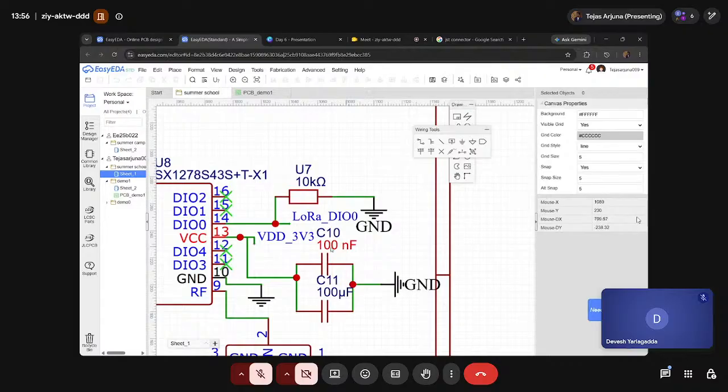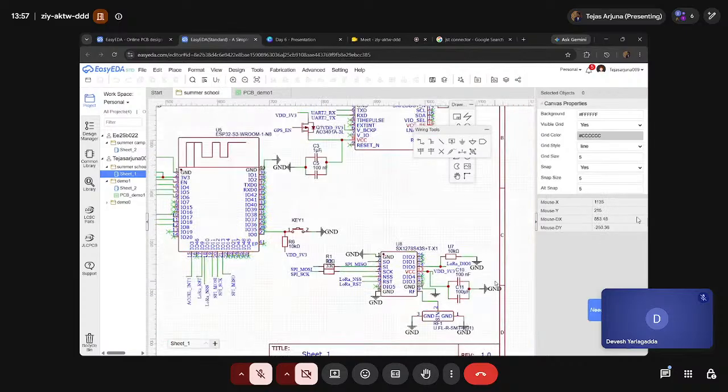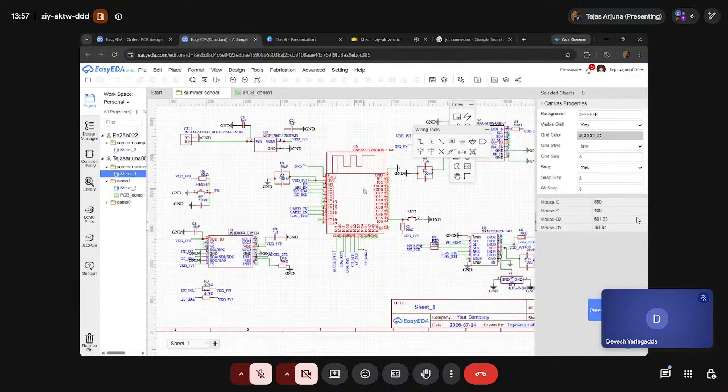So I wanted to show you the thing actually happening here. Whenever VDD is connected here, for DC current the capacitor acts like an open circuit. For AC current, it flows through this. So whenever the noise is there, the 3.3 volts acts as DC, the noise acts almost like an AC, and the 3.3 volts does not pass through here, while the noise moves along this path and goes through the ground. This was one thing I wanted to tell.